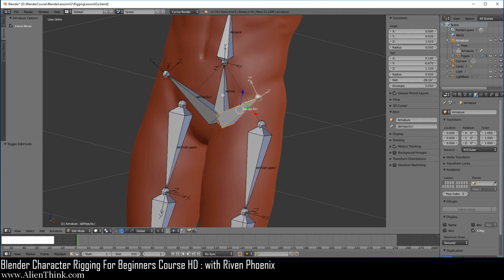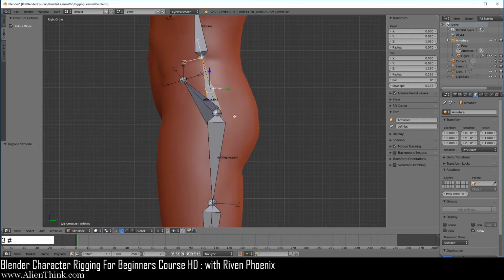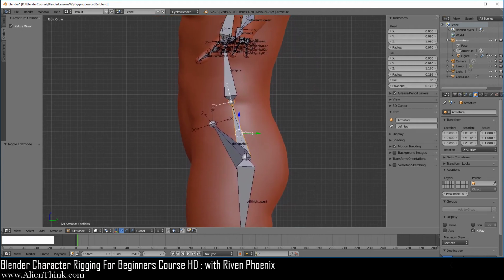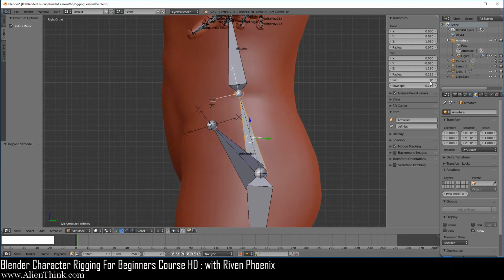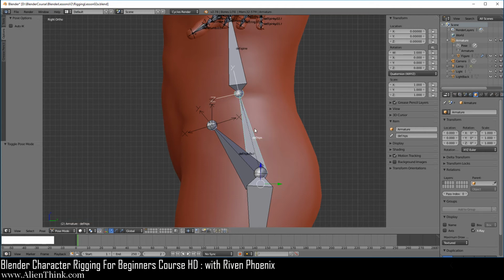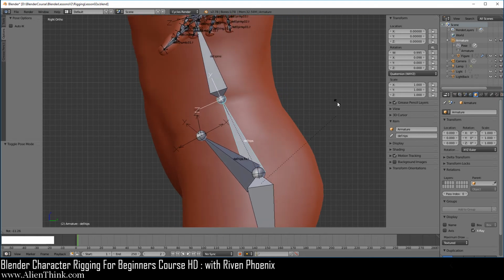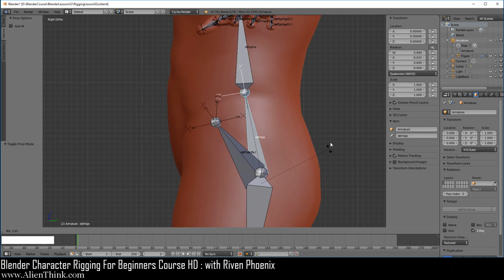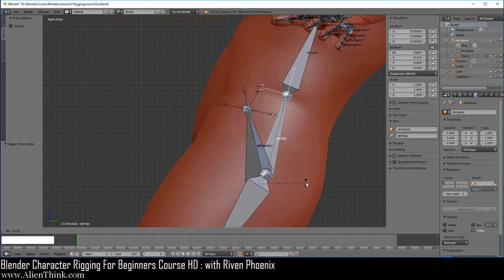Now let's go ahead and click on this hip bone over here, press the 3 key to take a look at this. Now over here, it'll state a 0. This is correct, right? And the Z is going to point to the left because this is going to be the major movement. Now let's go ahead and click on pose. Now you'll notice that when we press the R key from the right view and move this, the entire figure is going to move. So here is going to be the major movement and the minor movement, right?